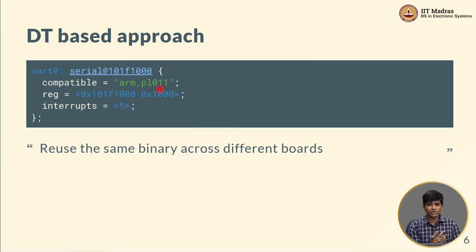And this loadable modules is an interesting idea that exists in Linux. It basically says that a driver can be a piece of code, actually executable code, which will just directly be loaded into a particular location in memory only when required. So in other words, I don't need to compile all the drivers right into the system ahead of time. I can go through my device tree, find out what kind of devices I actually have, and then load in those particular blocks of compiled code into the appropriate locations in memory when required. So this compatible, this word over here essentially helps us to identify which drivers we need to load into memory.